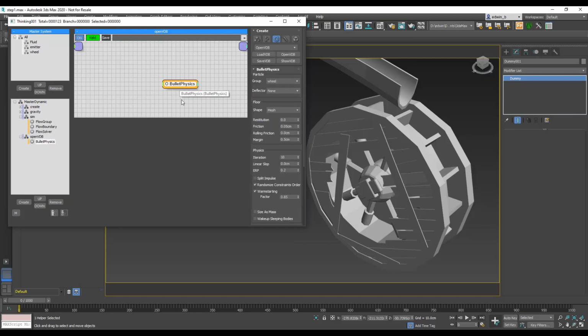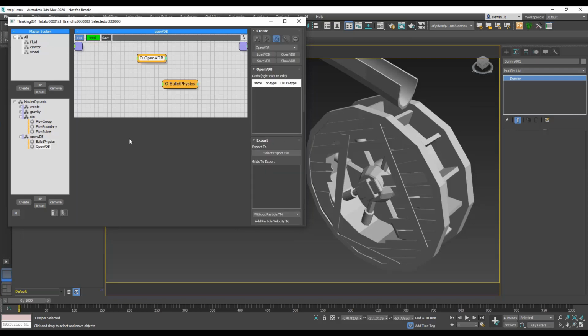The important part is when you start with OpenVDB, and there's also an order, you always have to work your way from top down. The first thing you do with an OpenVDB setup is create the OpenVDB container node. The OpenVDB container node defines our volume grid: how many volume grids I want, what's the name of the volume grids, and what type. So in that case, I want to have a distance field.